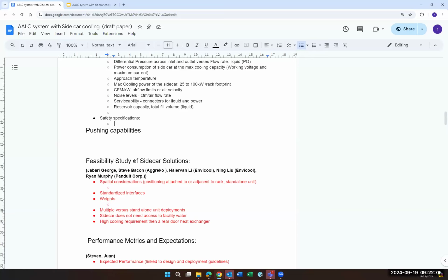Yeah, because the safety valve only comes into play if one part of the system fails. For example, in two-phase, if the fans are not running anymore but the pump is still running, then we increase the pressure, and with the pressure, maybe the system could be damaged. In that case, we need a safety valve, but only in a failure mode.